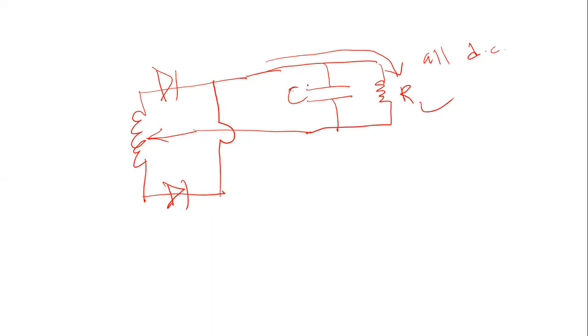But we know that this capacitor, depending on the frequency of the signal, has a certain impedance, 1 upon omega C, where omega is the frequency. So if the AC component has a significantly large omega, it will easily flow through this capacitor. Therefore, this capacitor creates a bypass route for all the AC component.